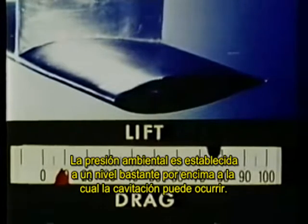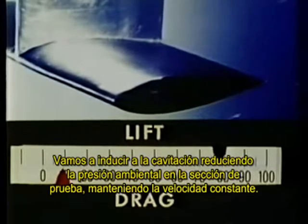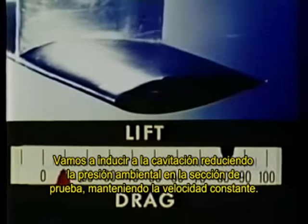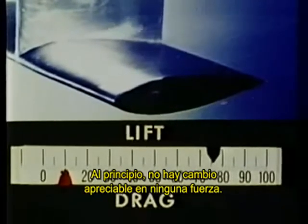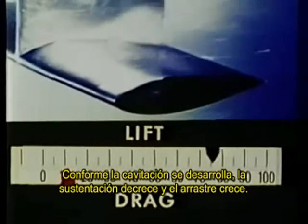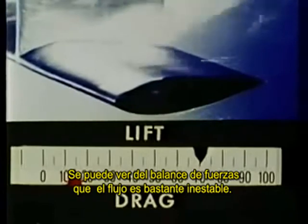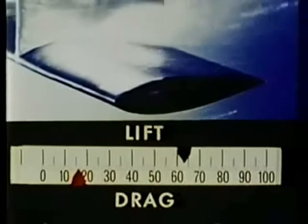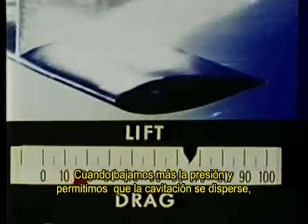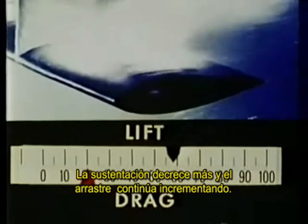The ambient pressure is set at a level well above that at which cavitation can occur. We are going to induce cavitation by decreasing the ambient pressure in the test section, keeping the speed constant. At first, there is no appreciable change in either force. As cavitation develops, lift decreases and drag rises. You can see from the force balances that the flow is quite unsteady. When we lower the pressure further and allow cavitation to spread, the lift decreases further and the drag continues to rise.